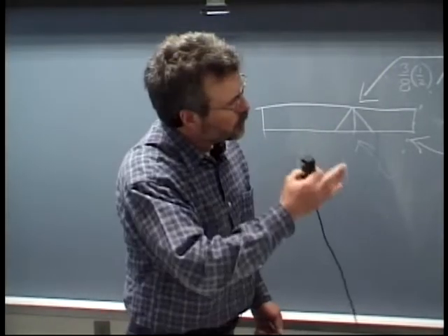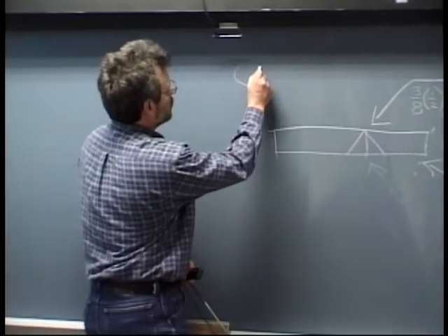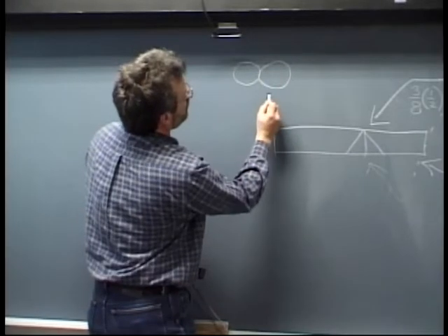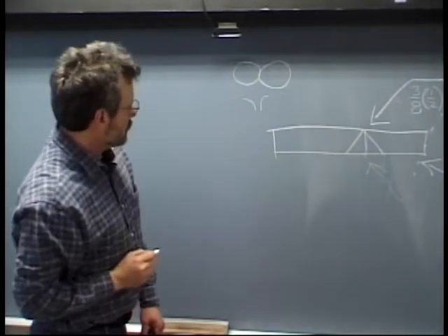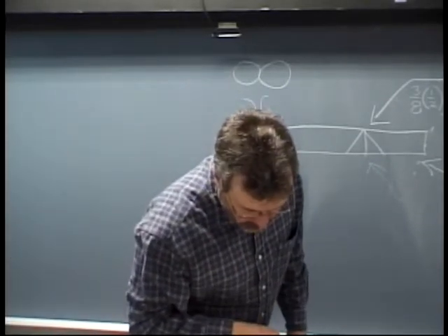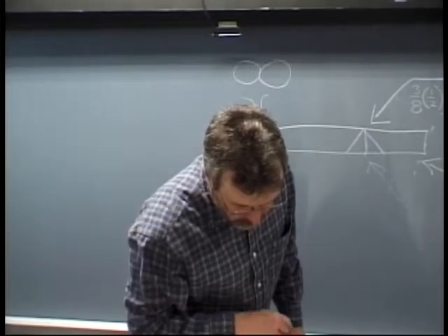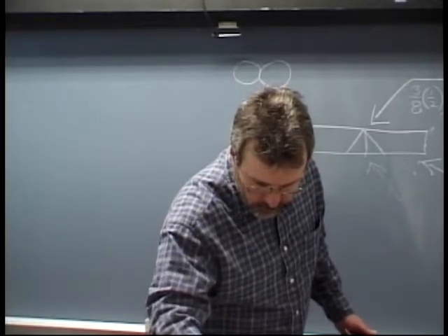Those pipes that I just showed you, looking down on the end of it, if we have two pipes sitting together like that, you can see from the roundness of the pipe that it would make a flare bevel. That's where they get their name from. In this case, the round bar makes a flare in the bevel, which will make it difficult for the welder to get the heat of the process into the root of the joint.